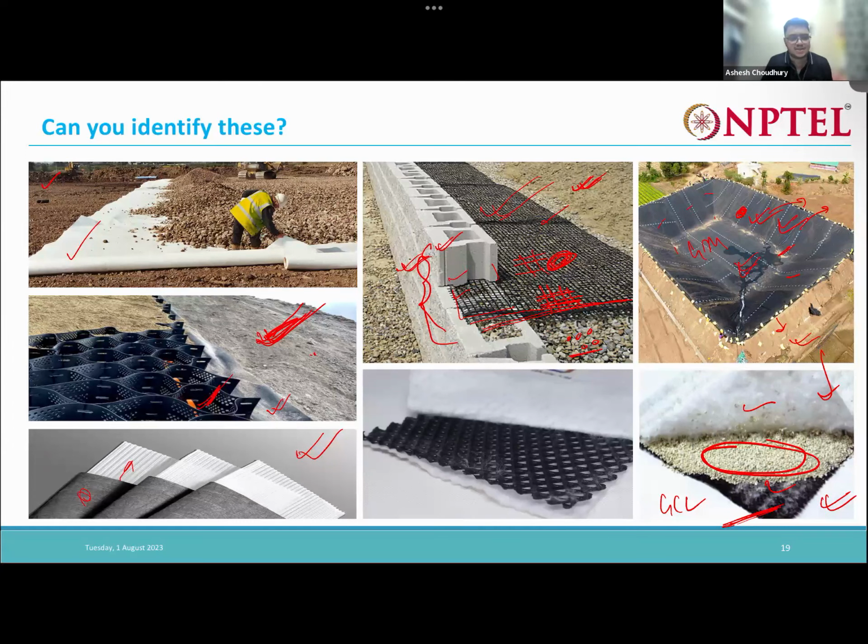You have studied, in the first week lecture, you have gone through the lecture, right? So you have studied the various types of geosynthetics. So we have already covered here, PVD? Geotextile. Yeah, correct. It's PVD. It's nothing but PVD, prefabricated vertical drains. So here you have an outer covering, and inside we have a core, right? So this PVD actually accelerates the drainage of water in a soil.